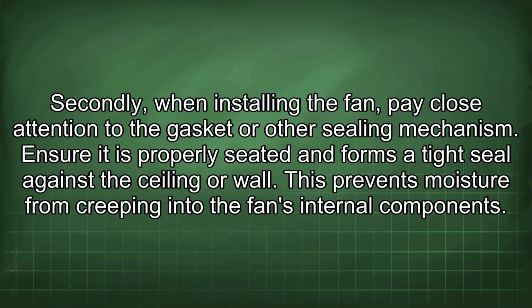Secondly, when installing the fan, pay close attention to the gasket or other sealing mechanism. Ensure it is properly seated and forms a tight seal against the ceiling or wall. This prevents moisture from creeping into the fan's internal components.